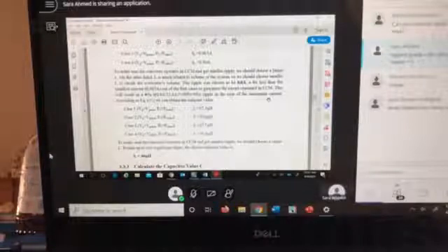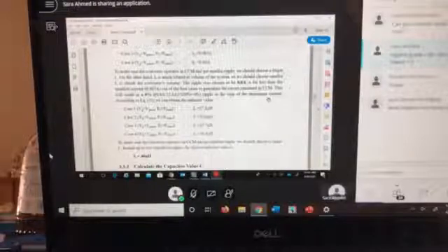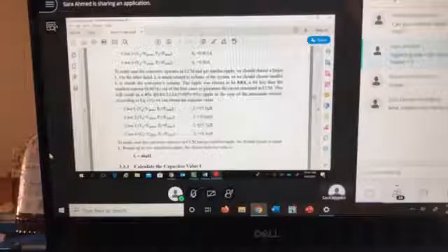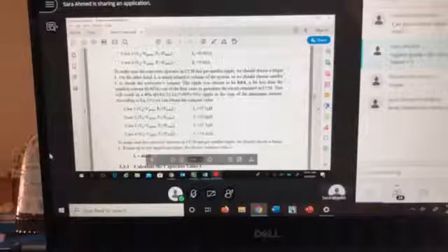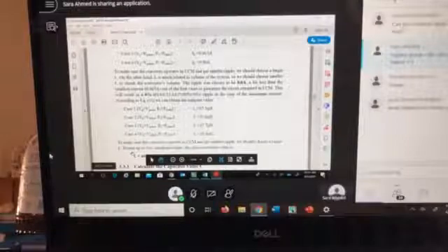So what can I do when I say worst case or the best, or what should be the best? The best would be always the largest. Yes, largest is not what you want, but largest guarantees that you can work in all conditions. So my largest here is going to be 37.7. So what can I do? I needed to round it because I was asked to round my inductances to 2 significant digits.